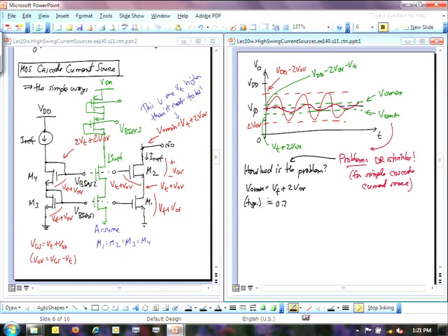What's a typical value for the overdrive voltage? Those are safe values, right? But bipolar is like 0.2, right? MOS, maybe it's 0.3 or so you're dropping across that. Depends on the device too, right? You can control that to whatever you want. But say it's 0.3 in this case. That means I got 1.3 volts as V output min, right?